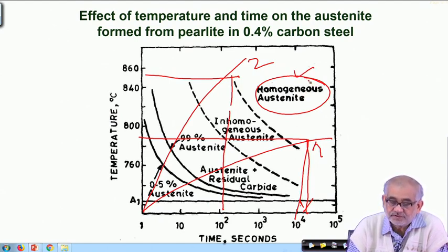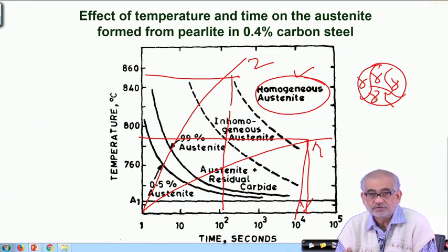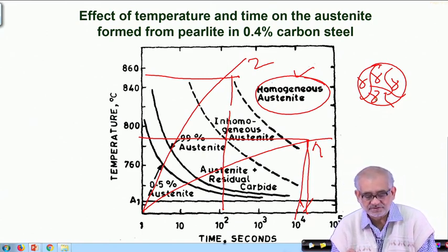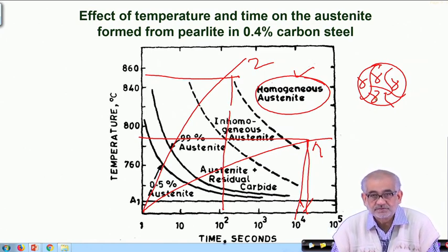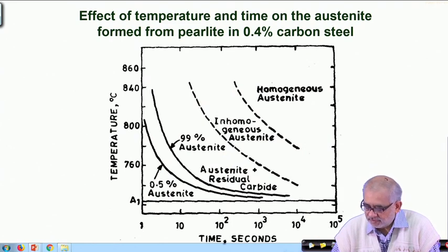So it is important for us, before we begin any such transformation, to make sure that the austenite is single phase. So the microstructure will be such a single phase microstructure, all austenite, and all of exactly the same composition. So homogeneous both in terms of microstructure and composition. Only then, on cooling, whatever microstructure you develop will be reproducible, precise, and give you the same set of properties that you want.